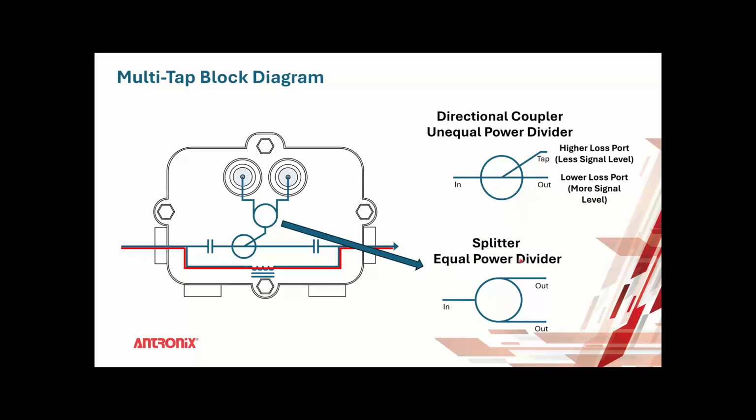What if there was just an AC pass-through with no RF choke? What would happen to the RF? The RF would still be there on the signal. So if there's no AC choke, the RF would still be there. But if it's accidentally cut out, this is tuned to the circuitry here, so your RF could be affected if it was damaged and cut out of the board.